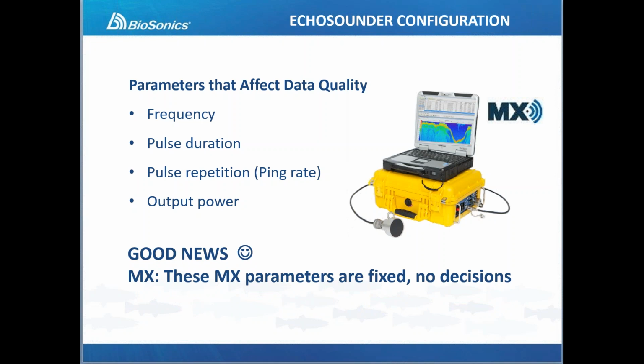We've done all that research and testing, and so the system is provided out of the box, ready to go with these settings all optimized. Again, we have a 200 kilohertz transducer. We emit a 0.4 millisecond pulse, and we ping at 5 times a second.